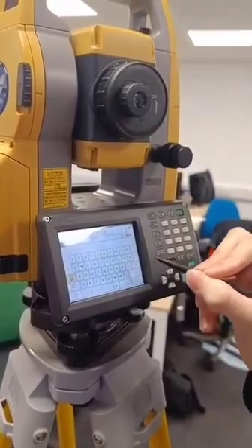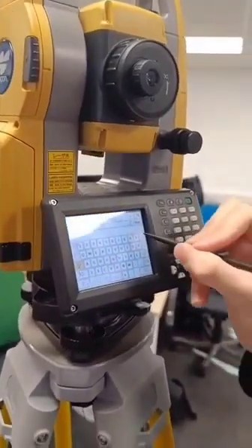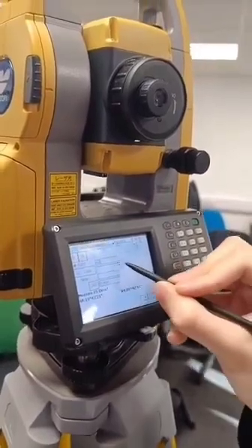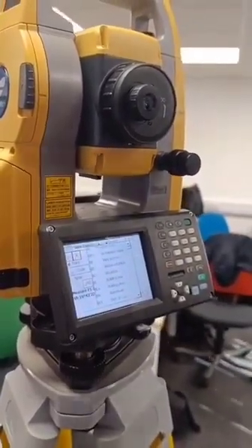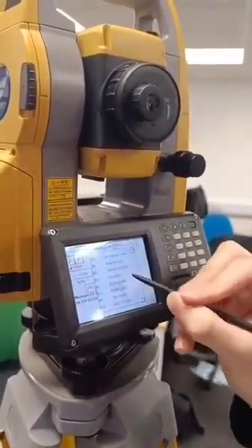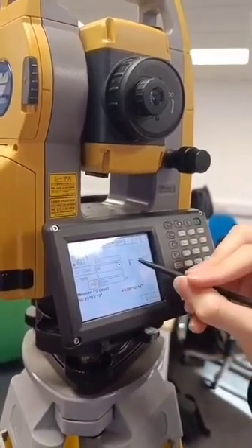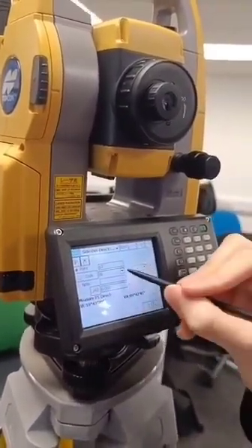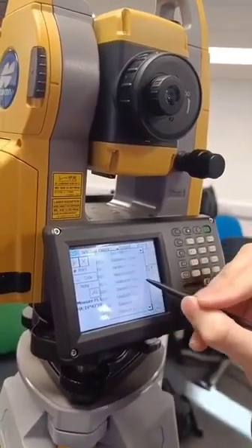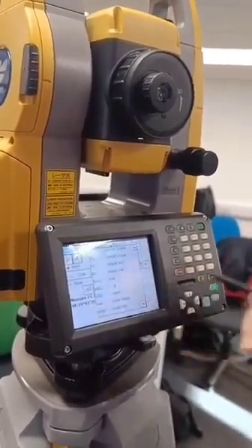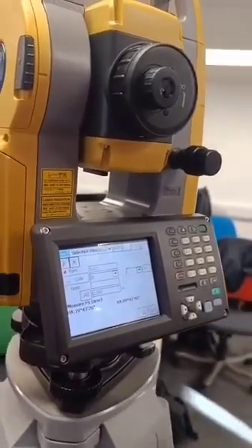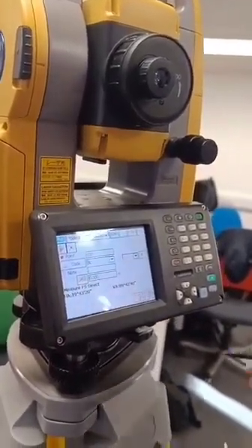Change your point code. You can start at 100, or you could just change it to 001. I'll just leave it as 100 as the default. Code. Basically, this code is telling the machine what you're measuring. The default that you would use is building line, because it just connects all the dots within this code sort of thing. But if you want to get in more detail, you can change it to stuff like wall down here, window. I used it in my one, but it's not really necessary. It just changes it on the list for a bit more detail.